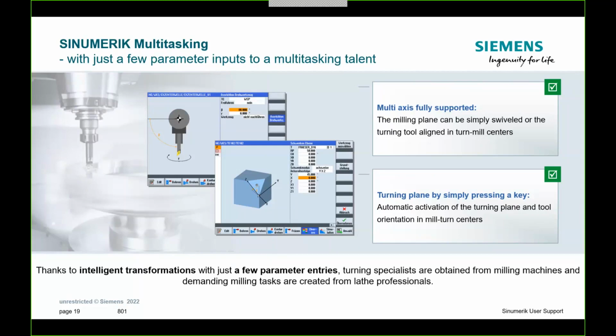And I really suggest, especially in conversational programming, that you use the kinematic independent or the beta and the gamma rotations for your orientations of the tool. So what happens is when we set this, the whole coordinate system shifts. So we're actually changing the tool, not the part.